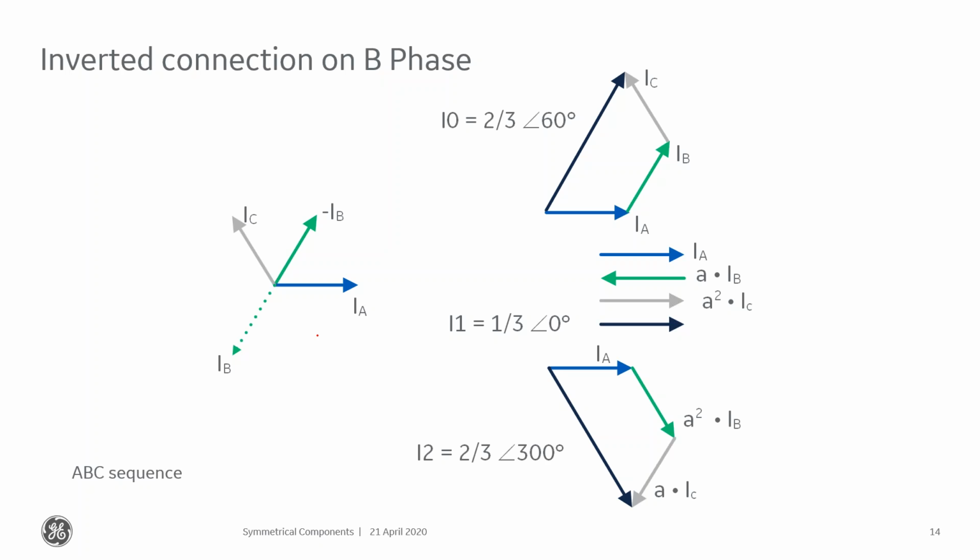So the only way that I can have an inverted phase like this is if I have a wiring error. If I look at B phase here, it should be sitting down at -120, and it's really sitting at about 60 degrees. So that's not right.